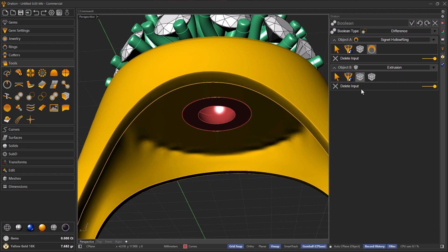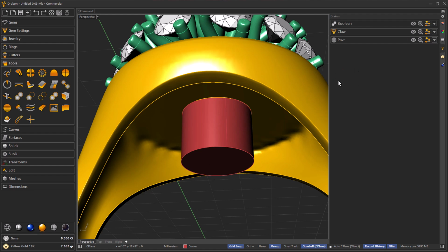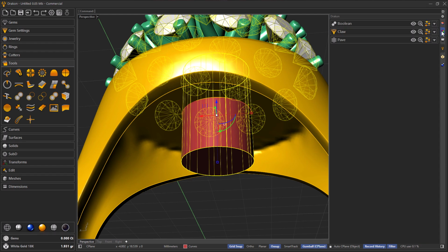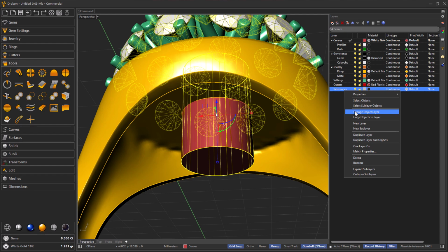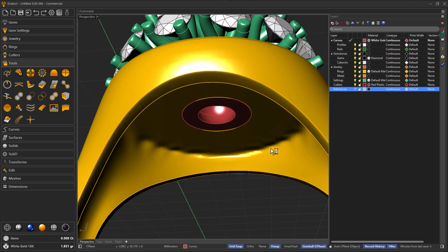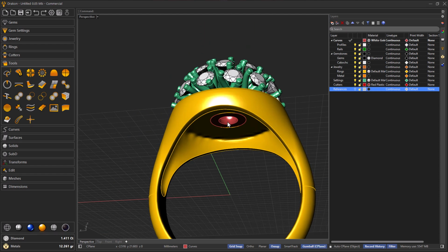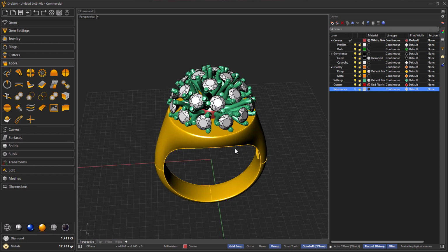So what we can do when we use Rhino objects is just not use the option to delete input, and it will be available for further editing. So we can just, for instance, change the object layer and hide the layer, and this is how it's properly managed.